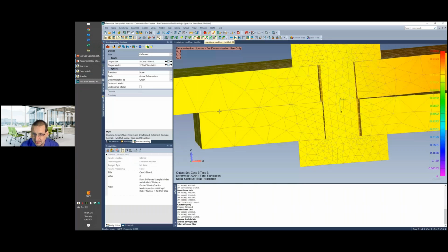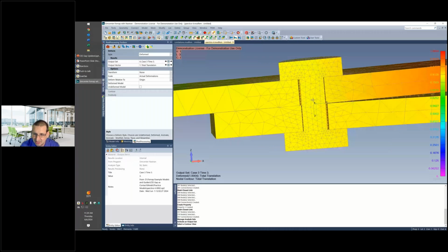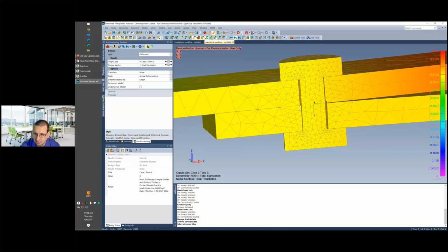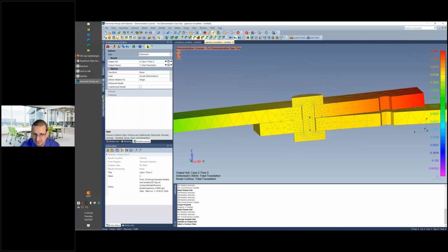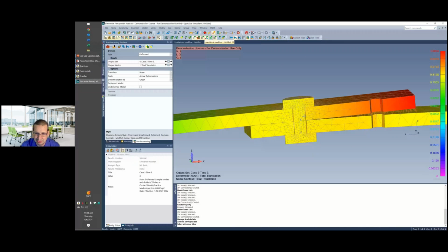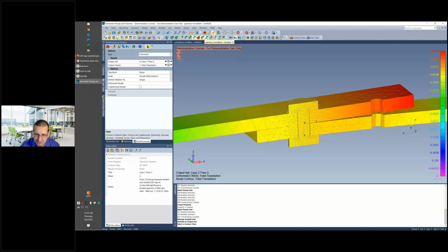We're also seeing some motion over here, but it looks like the stability stiffness that I added has limited the amount of motion that we're seeing. So I could try running this analysis again with an even smaller value, or just neglecting that particular aspect of it. This model is a little more statically stable due to the symmetry plane, but without the symmetry, when I was first running this model with the full bolt, rotation issues were definitely a problem.